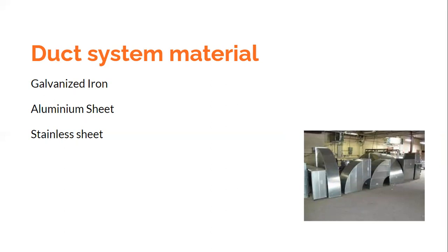The horsepower of the fan would be more to deliver the required quantity of air against the system head or system pressure. Okay, so we are again stressing this because that is why the classification of ducting systems is important. Similarly, when you talk about velocity, if the velocity increases, the noise level would increase because the air motion would increase. Thus, on the two counts, the velocity of the air in the duct has to be kept at a reasonably low level.